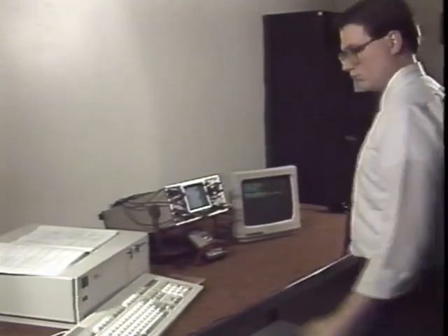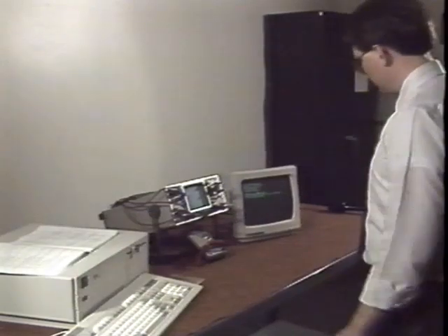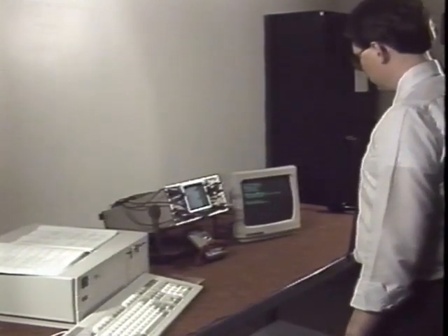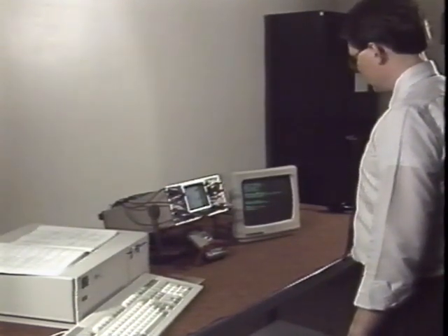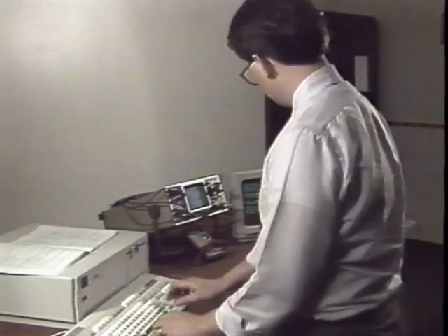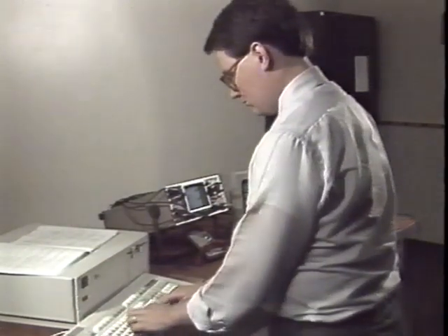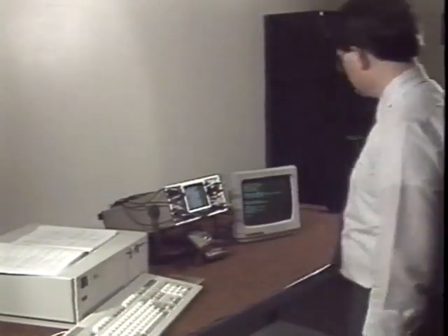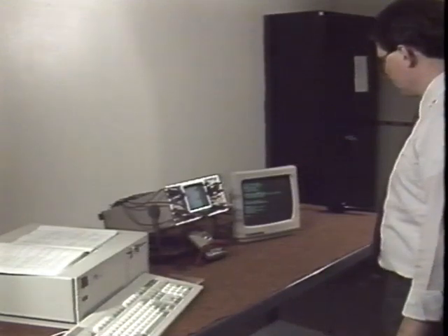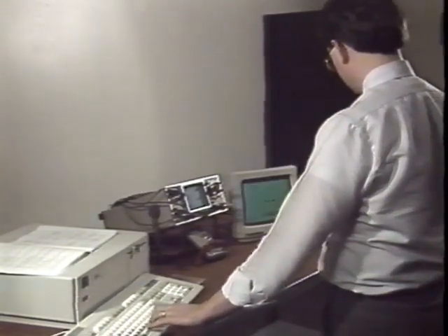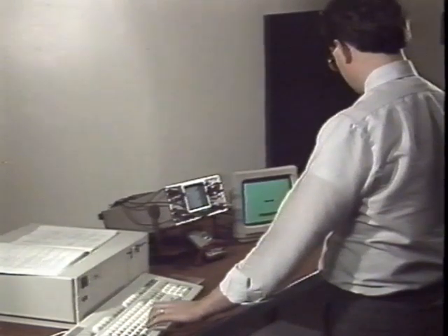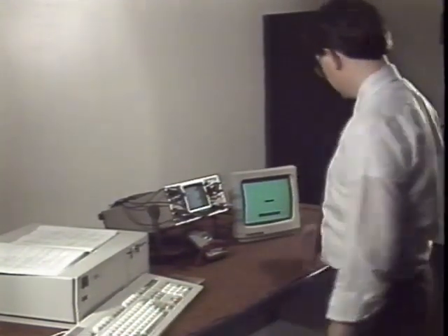First, remove all jewelry and place an isolation transformer in the monitor's AC input path. Connect the monitor to a computer's video output and boot a diagnostics diskette. Select a video alignments program. We will use this software to generate the patterns needed for the alignment. Consult the service manual before beginning any alignments. The adjustment points, and in some cases the procedure, will vary for different models.